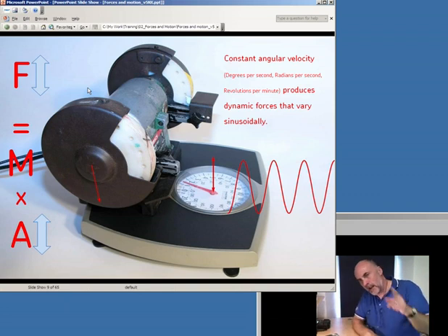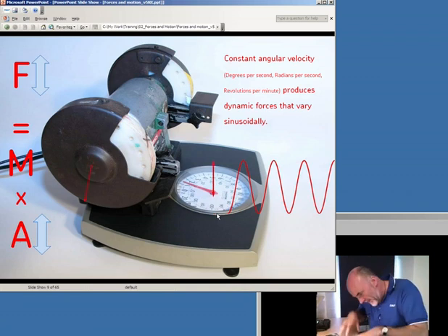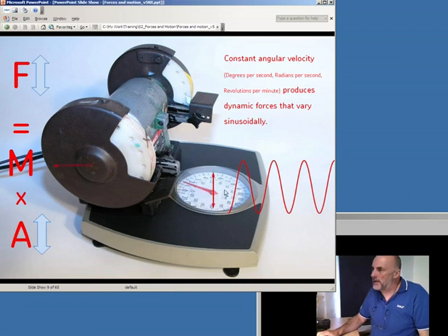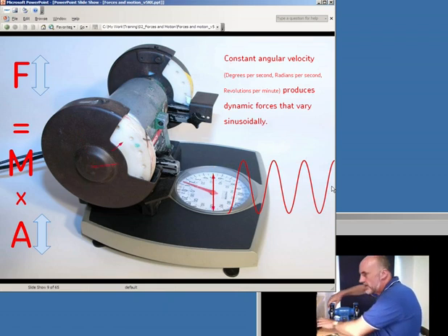And as that vector, as we call it, rotates through 360 degrees, if we measure in just one plane the forces that are going into the foundation of our machine, you will find that you plot this thing called a sine wave. Now, it's not very easy. I have a machine here. I've got a blue benchtop grinder here.